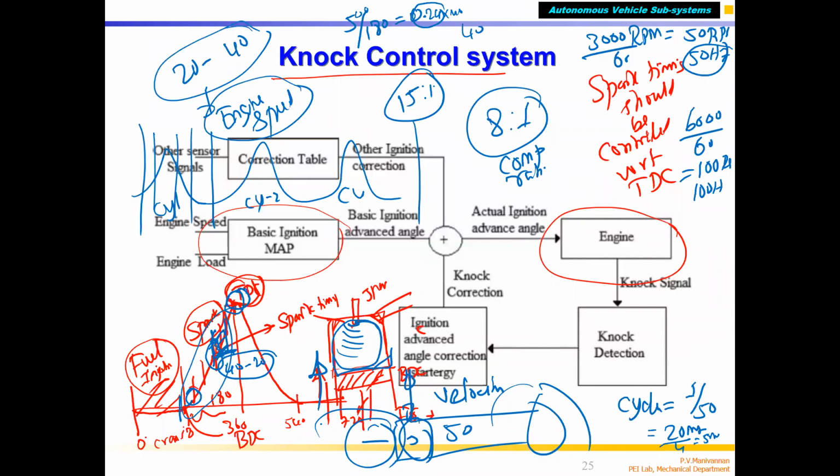Combustion duration for petrol is approximately fixed, depending on the fuel. Approximately, but it slightly varies depending on compression ratio, 8:1, 10:1, all those things, many conditions, but generally it is constant, correct? Combustion duration will generally be in the order of milliseconds, correct?